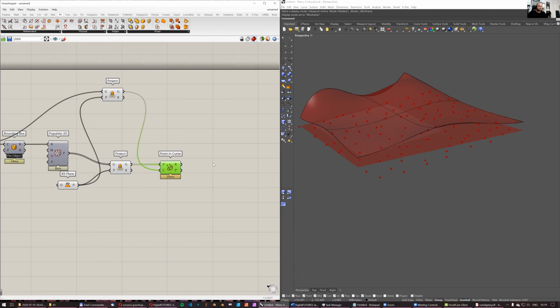So in Grasshopper, you can convert many values to different types. One type that you can convert is a number, and you can convert it into a Boolean. Boolean is basically only true or false. And the conversion goes: 0 is converted to false, anything else is converted to true.